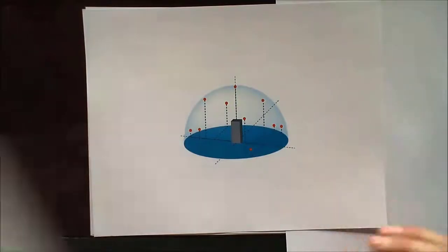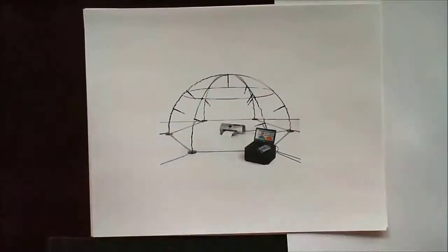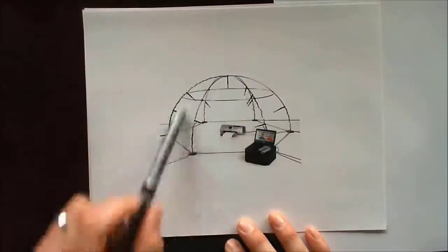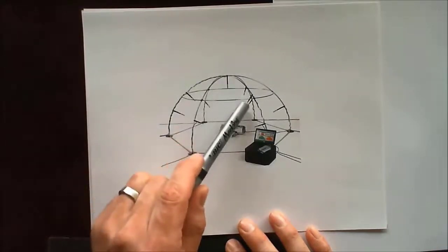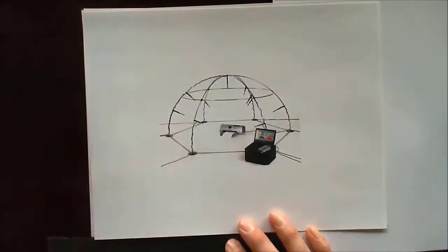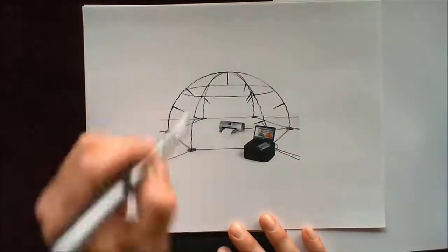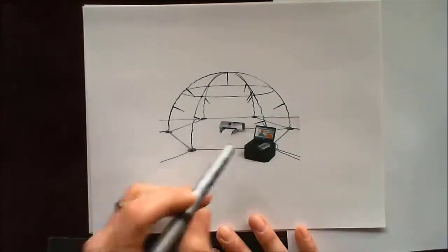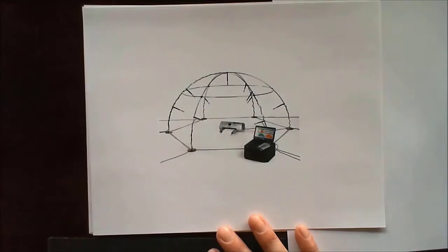If I look at a real test setup, this is an actual sound power test. In this case, it's on a computer printer. But you can see this hemisphere that goes all the way around the object as well as over on top, and these are all my microphones. And they're all pointing directly at my noise object or sound source, and they're all the same distance away in this hemispheric condition.